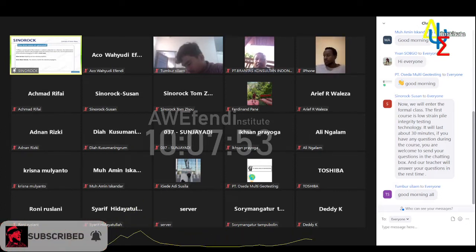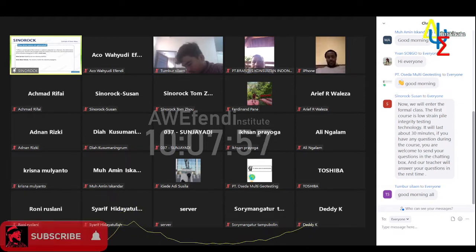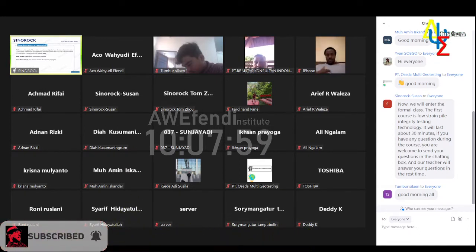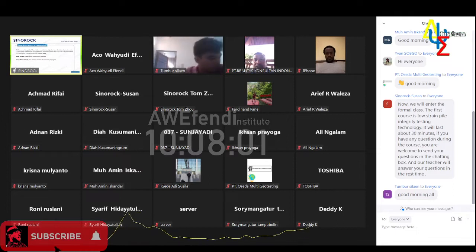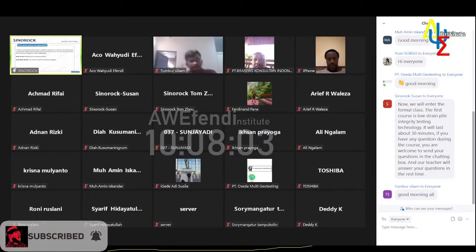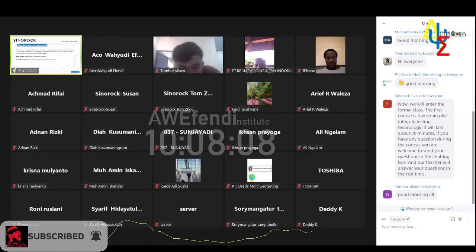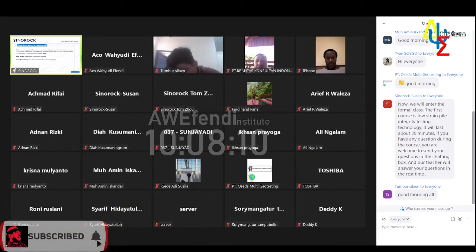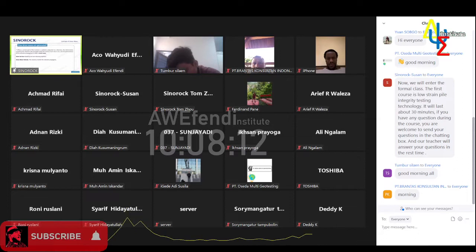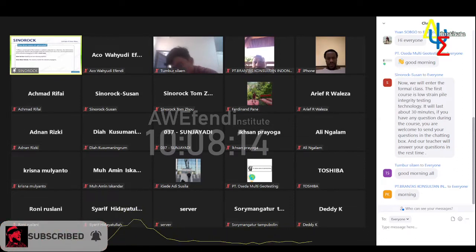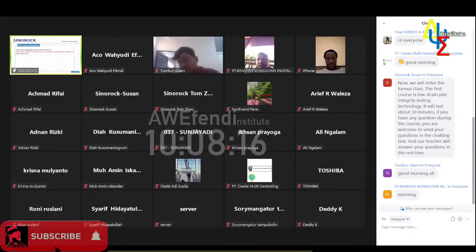This phenomenon of disturbance propagation is called stress wave propagation. The interface between disturbance and undisturbed is what we call the wave front. When a stone is thrown into the water, ripples slowly spread out from near to far. So the part of the ripple vibration is the disturbed surface, and the part without vibration in the distance is the undisturbed surface. The wave speed of stress wave refers to the propagation of this disturbance.